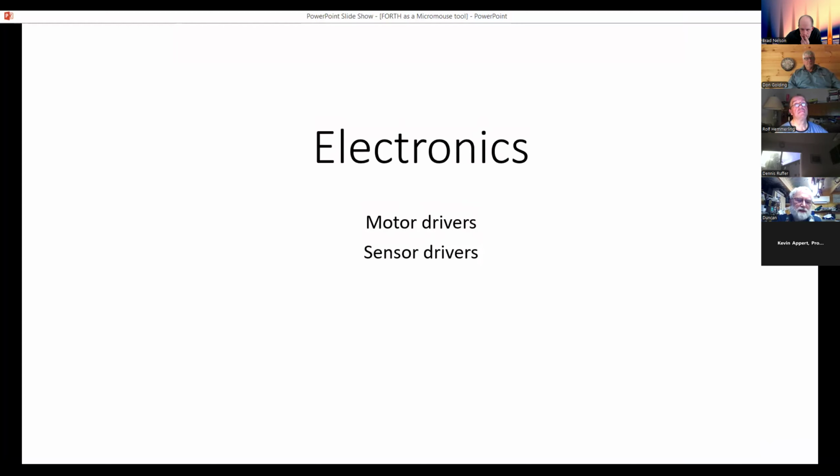Most mice use reflected light sensors for detecting wall or line position. The amount of detected reflected light is, in principle, proportional to the inverse square of the distance. The presence of bright ambient light, sunlight, makes life difficult. What we do is that the system turns a bright LED on, takes a reading from the photosensor, turns the LED off, takes another reading from the photosensor, and subtracts the second one from the first. So you're subtracting the ambient light from the reading.